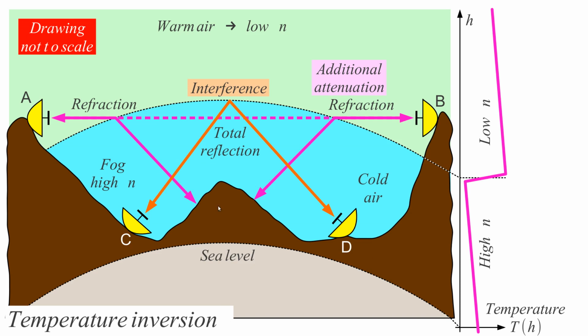But we also have refraction. We have continuous refraction just in the undisturbed, well-mixed atmosphere, and even that refraction has some effects on radio waves, but it's too much for today's lecture. We may also have additional loss on rain or snow because of scattering on raindrops or scattering on snowflakes. We may have many other effects.